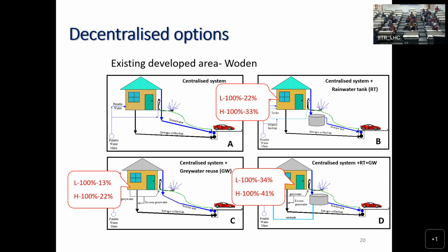So by simple mathematics you can work out, if you are providing rainwater and grey water, how many homes you need with both systems to achieve 25%. Similarly with high water demand management, if you are achieving 41% with 100%, how many homes in total do we need these types of systems in to achieve 25%.